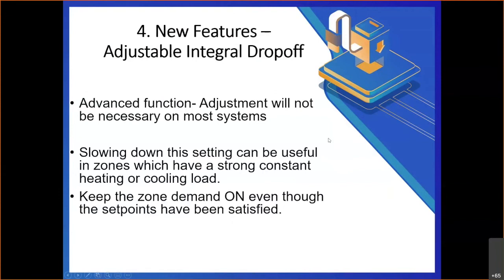We're not going to get into the depths of proportional and integral and how that is calculated, but as the integral accrues, we keep driving our demand up, and eventually we reach a point where we have operated the equipment in such a manner that we have satisfied our demand. Once we satisfy the demand, there is no more proportional response, but there still is an integral that needs to decay, if you will.